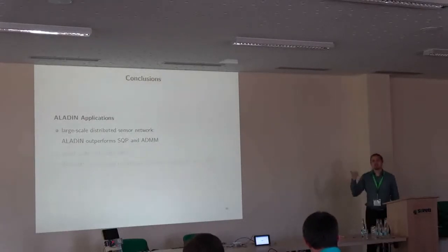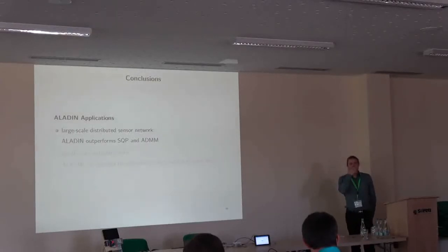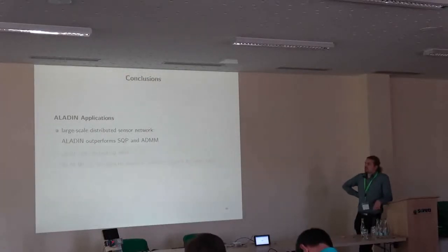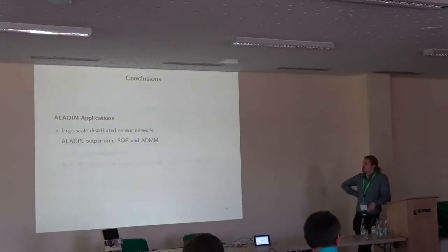We have shown this on various case studies. We have shown it for the lasso problem, where we applied it to a convex least squares plus 1-norm type of objective function. But we've also compared Aladin versus ADMM for that optimal power flow test case study, where we see that we get major advantages in terms of the convergence properties and computation time of the algorithm.